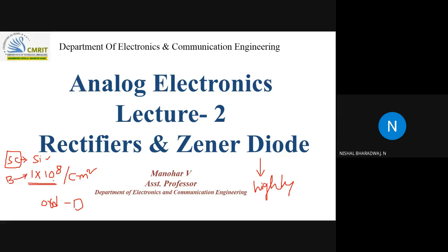Those many number of molecules, sir. Yeah, I am saying the boron doping concentration to dope silicon is 1 in 10 power 8. So what is the meaning of this? 1 in 10 power 8 means how many boron atoms will be there for how many silicon atoms you are doping. So the meaning here is 1 boron atom for 10 power 8 silicon atoms. If I am saying 1 in 10 power 8 per centimeter square, it means in per centimeter square area, I am using 1 boron atom for 10 power 8 silicon atoms.